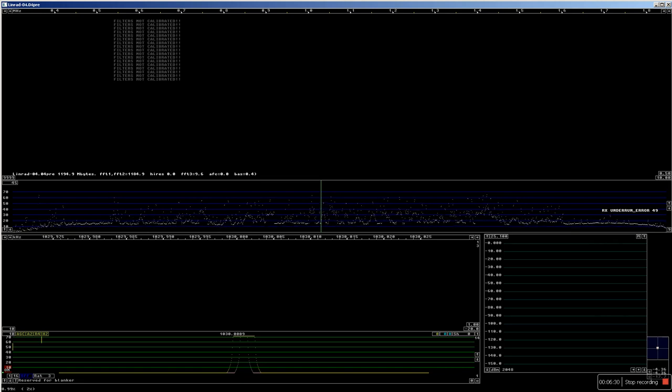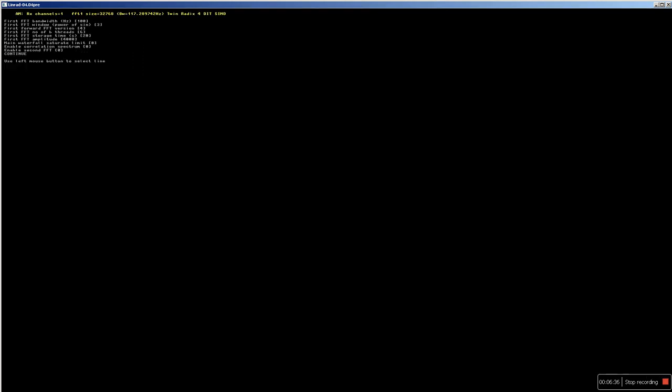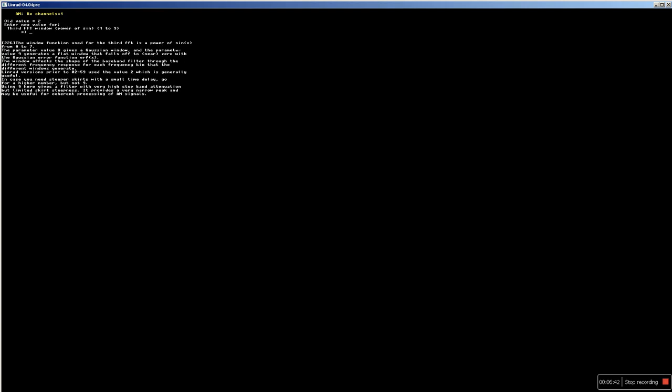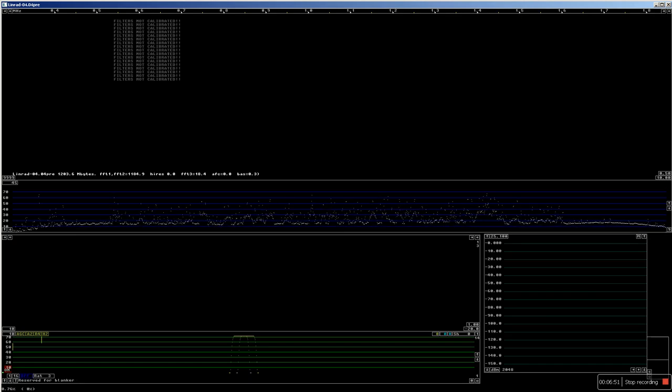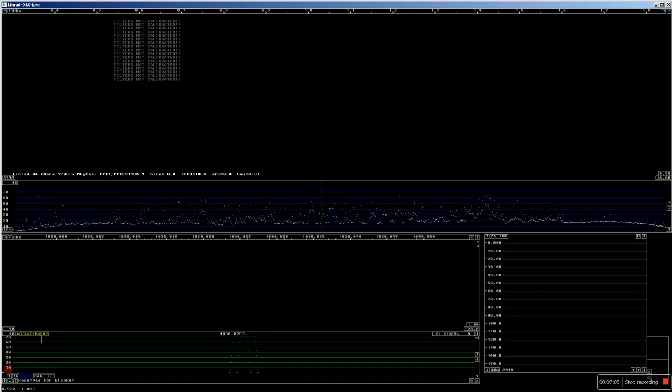And I forgot one more thing that I could look at. That is X, P, and then enter, enter. I can put a more beautiful filter here. I make it 8. That's a Gaussian filter. That will make the resolution better on the carriers. Like this. And then F3.